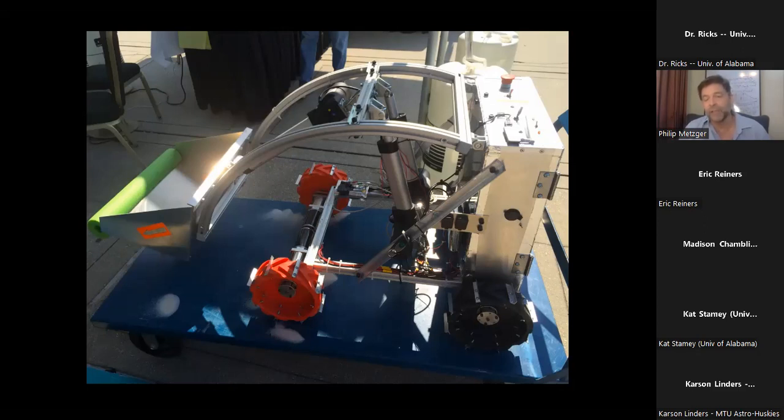So you can either have chains that connect the front and rear wheels together mechanically, or you can have encoders on the wheels with electronic feedback to essentially chain them together in the electronics. That will entirely prevent wheel diagonalization. And we've seen teams do it both ways.